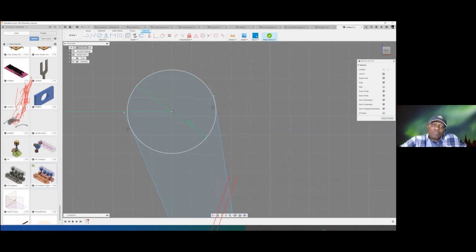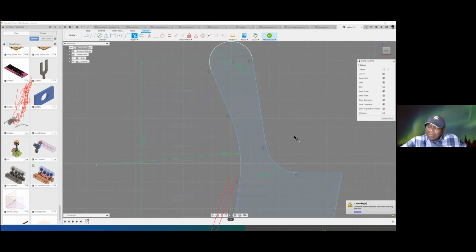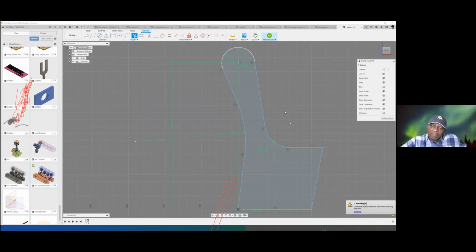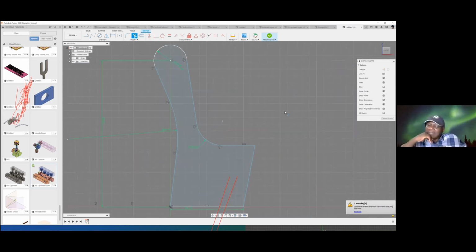I use the trim tool in the modify. If I take the trim tool and click this, it knows precisely how much to trim. It trims all the way to the point, and then I can trim this one. I will also want to trim this part so that you can see this is just the crest of that circle. I don't need the whole circle. And then once I'm done, I can allow the thing to fit the plane. I don't like where it has thrown it, so I move it back here. So you can see we're getting somewhere gradually.